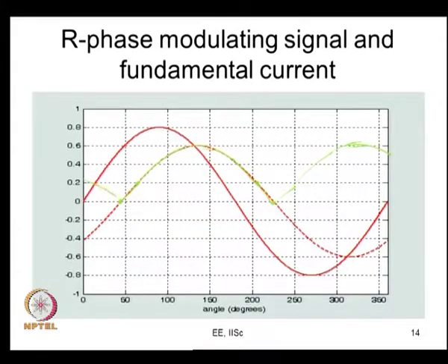Like this. This is your switching energy lost. And what is its average value? It is a rectified sinusoid. So, you can always say it is 2 by pi times its peak value. So, it is fairly simple to evaluate the average value here now.